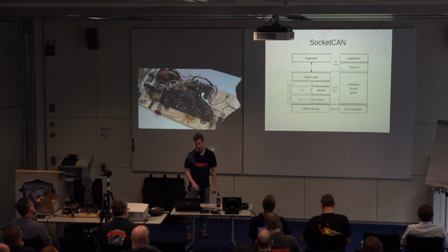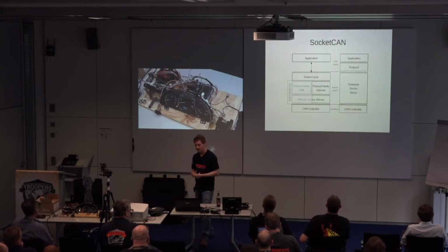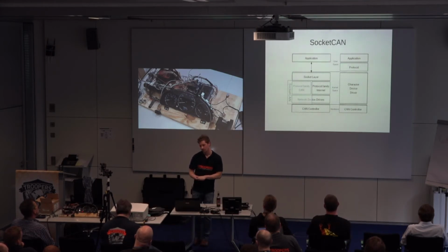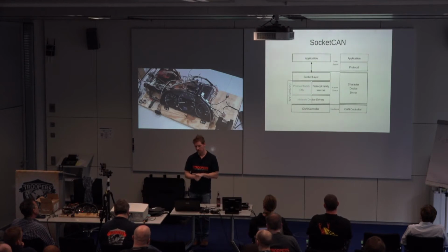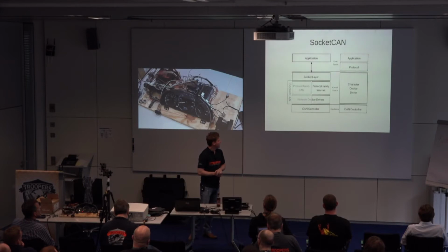One of the things we're going to use today is one of my favorite drivers for this type of stuff, and it's specific to Linux. If you guys have laptops here with Linux on them, there'll be some things where you can play along. So SocketCAN runs in the kernel. It's a kernel driver, and it will connect your CAN devices to a normal socket.